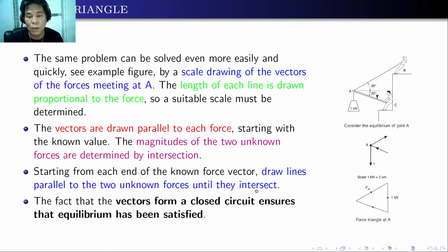So what does it mean? You have to draw your structure in a scaled manner. You have to scale it, and then with that drawing, you can just draw the forces parallel to the members of your structure. The fact that the vectors form a closed circuit ensures that equilibrium has been satisfied. So as you can see, we have this structure.